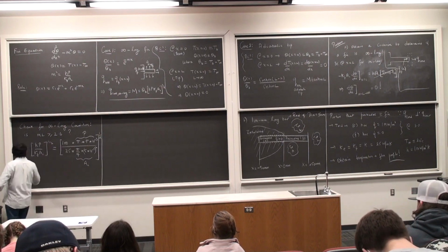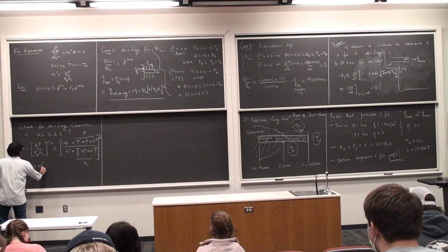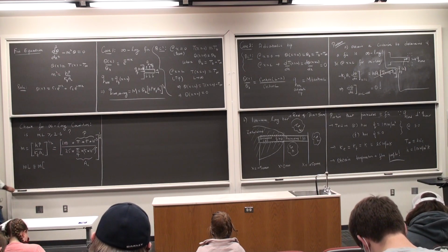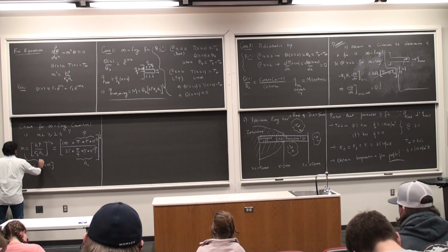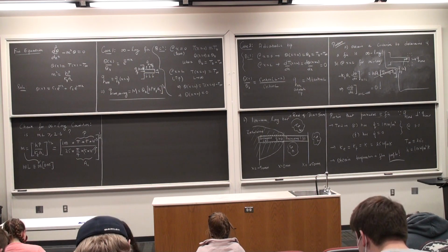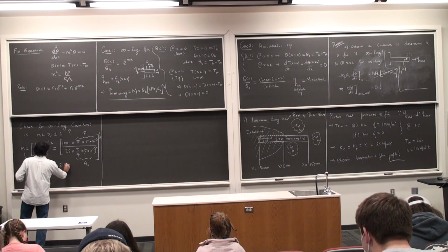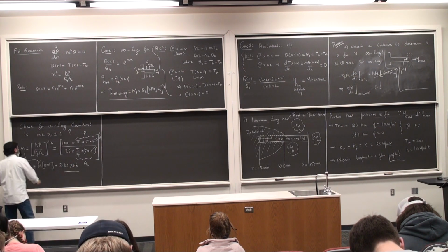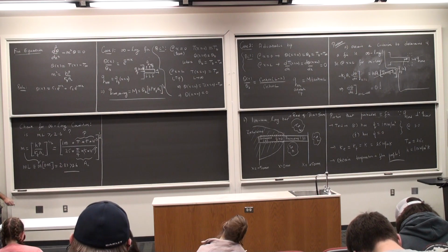You can plug the numbers. M times L, which is m times the length of the fin portion, which is 50 millimeters, so 0.05. There you plug in for m from there. This gives you 2.83, which is greater than 2.6. So the fin is infinitely long. So this is how we prove it. Okay?